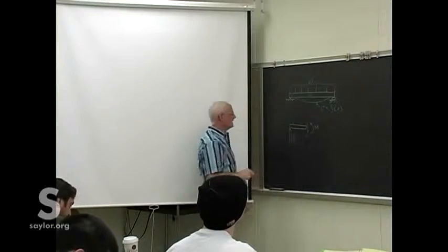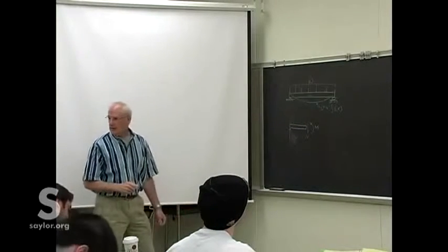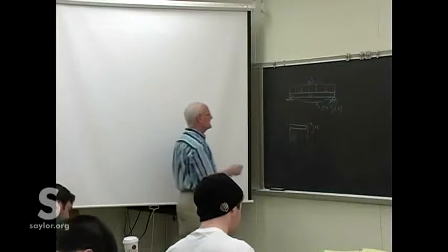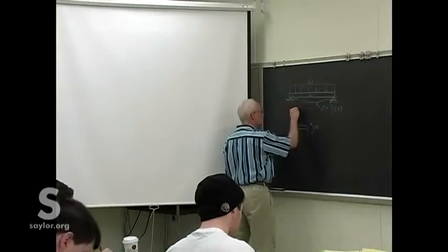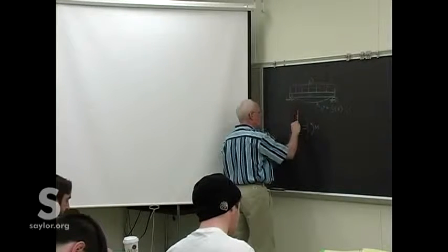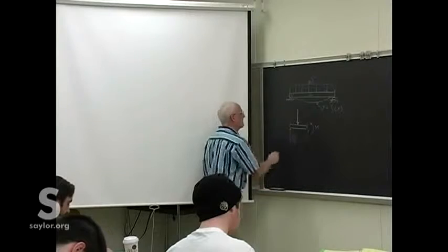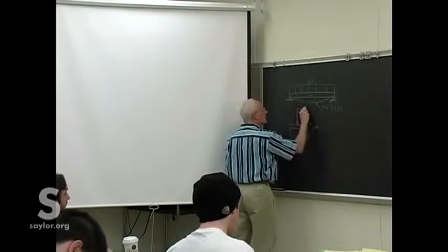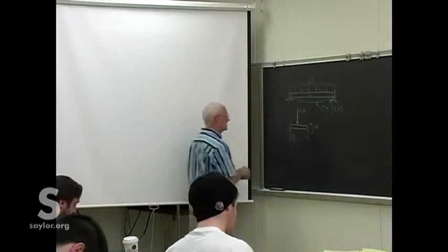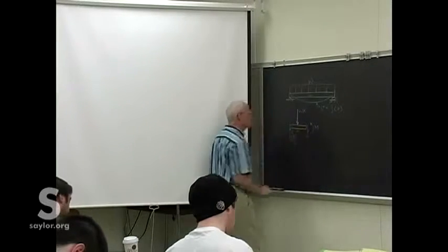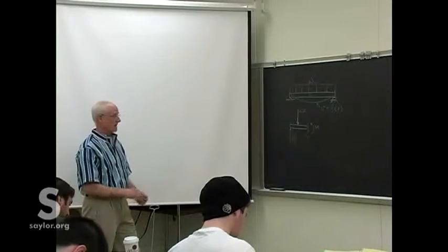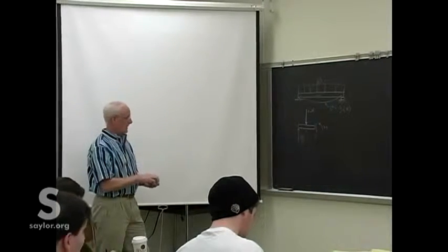We've got this distributed load, but remember to figure out what V and M are, we'll replace that with an equivalent single load just to get the right value here. So we'll replace that distributed load with a single point load of Wx, because this little section is just we're just trying to find out the moment as a function of x, and then we can start integrating backwards.